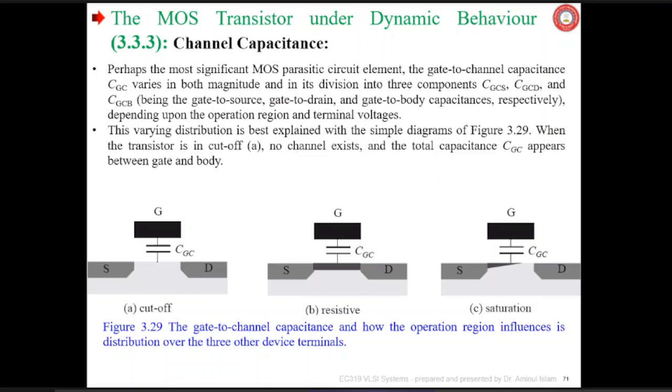Capacitance of the MOSFET at its different modes or regions of operation, when the MOSFET is cut off, linear and saturation. When the MOSFET is cut off, then the capacitance CG is nothing but CGB, the body terminal being on this side. Let me denote here between these two plates, one is the gate here, poly, and the other one is Si.